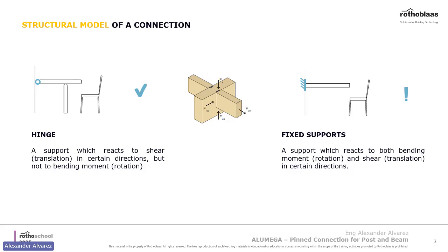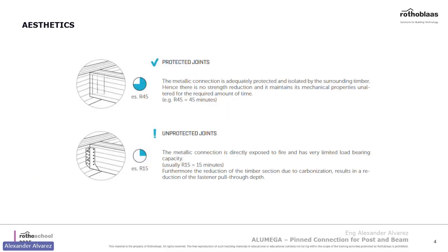So that's why you see a lot more hinge connections when it comes to timber. Usually you see them like hangers. You connect the beams or the joists into either a knife plate connector or one of these bucket connectors where you just slide the beam on top of it. They both get the job done. They both hold the beams, the weight and the load.